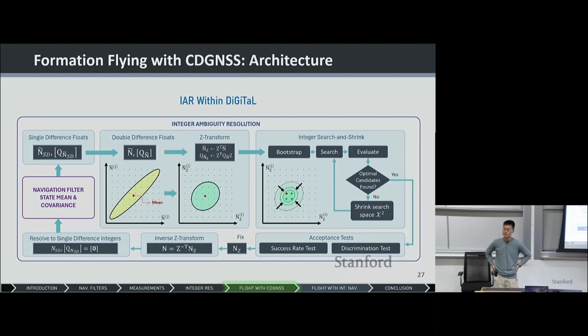The requirement for GRACE and TanDEM-X to do millimeter accurate relative position estimation was on the ground, to process the synthetic aperture radar data or the accelerometer data of GRACE, so to generate a science product that doesn't need to be generated in real time on board. This is done offline over a long period of time using data that are downloaded from the mission. It would be reckless to implement something of that complexity on a spacecraft if it's not required.